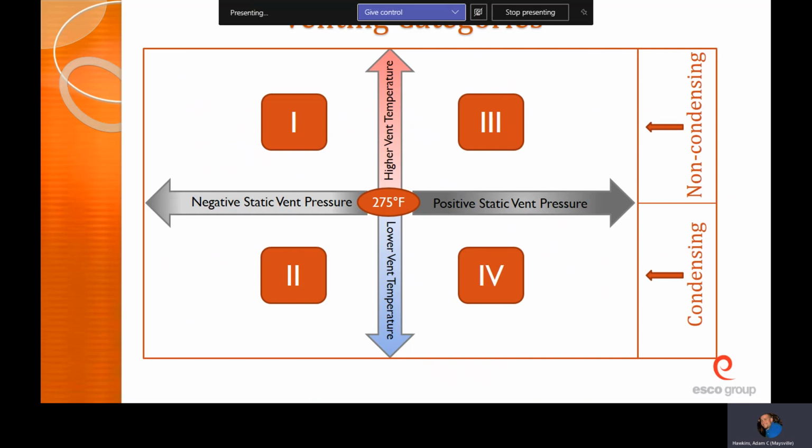So it's imperative that you put the right material and that you install it the correct way. And that's one easy way to tell. If you're looking at a furnace, that's a dead giveaway. If it's got a metal pipe, it's an 80%. If it's got PVC pipe, it's 90 plus.